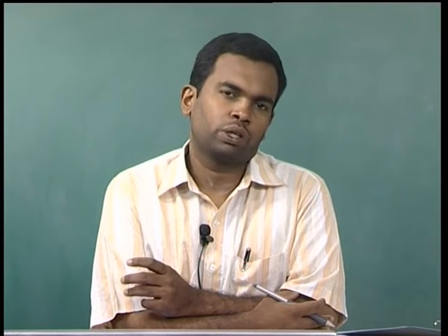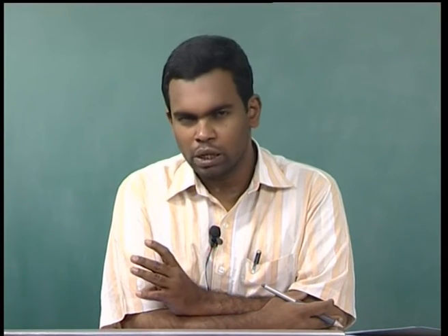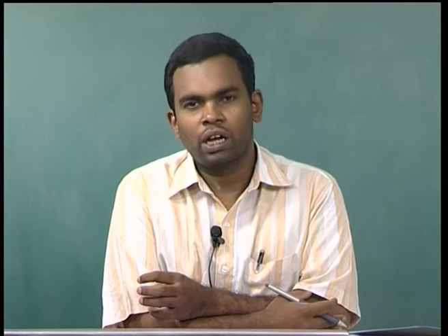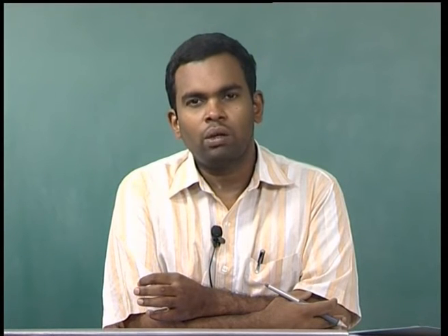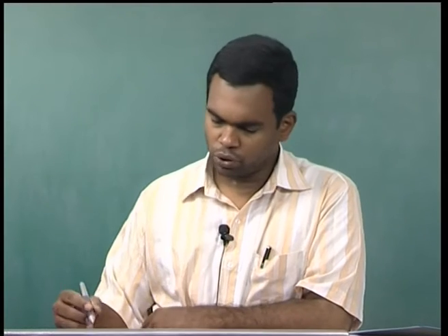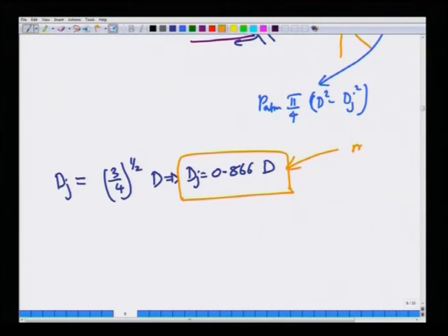That is because of the fact that the nature of assumptions that we made in these two cases are different. In the differential energy balance, we said that the viscous losses in the jet are negligible, whereas here we said that the tangential component of the viscous shear stresses are negligible. So, they are not quite one and the same. So, that is the reason why we get different results when we use these two approximations. It so happens that this result is more close to experimental value